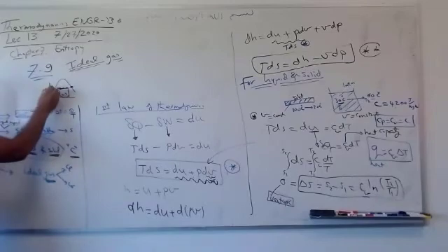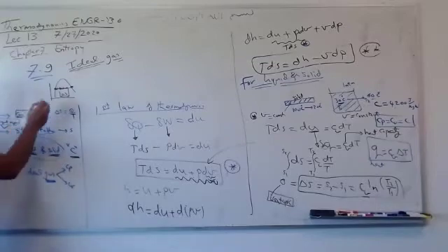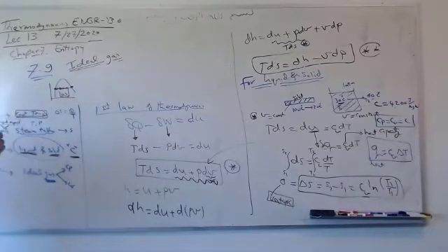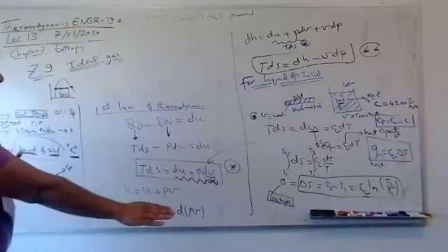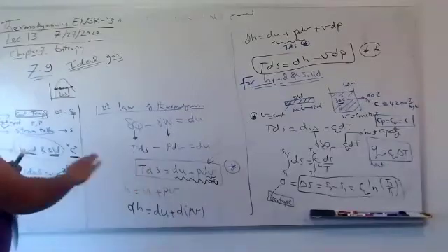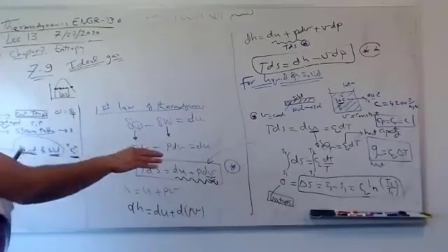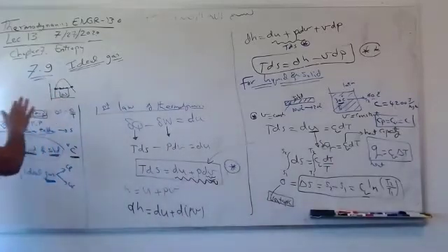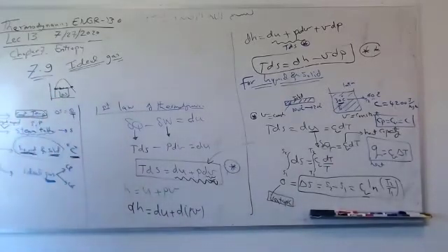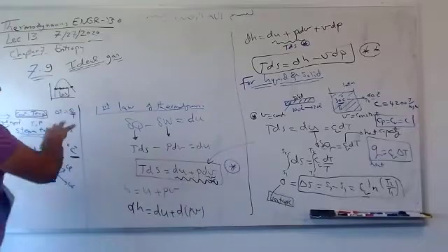Liquid became vapor, more vapor, more vapor, until complete vapor at the saturated vapor line. So we have delta S. There is no increase in temperature, but we have delta S. Unlike solid and liquid, it's impossible to get delta S without changing temperature because there is no phase change. But here we have phase change. That's why the heat is consumed to transform the phase from one phase to another.